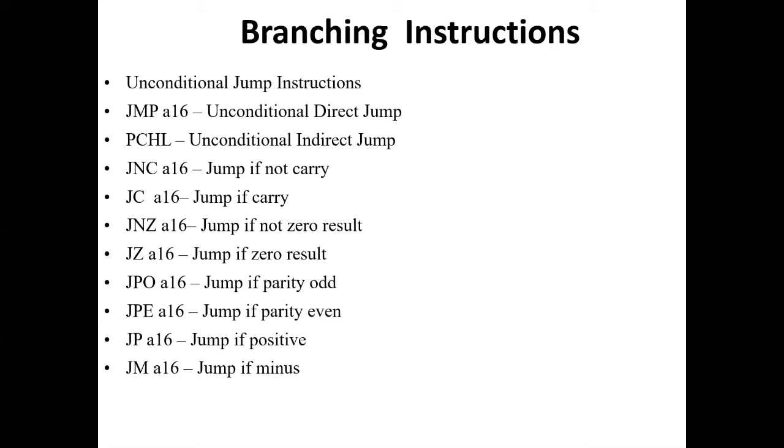Next are the conditional jump instructions. First one is JNC A16. JNC is a mnemonic which stands for jump if not carry, and A16 stands for any 16-bit address. This instruction is used to jump to the address A16 provided in the instruction only if carry flag value is 0. If carry flag value is 1, program flow continues sequentially.